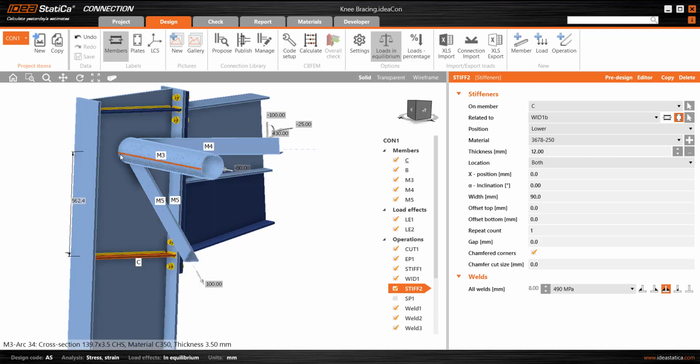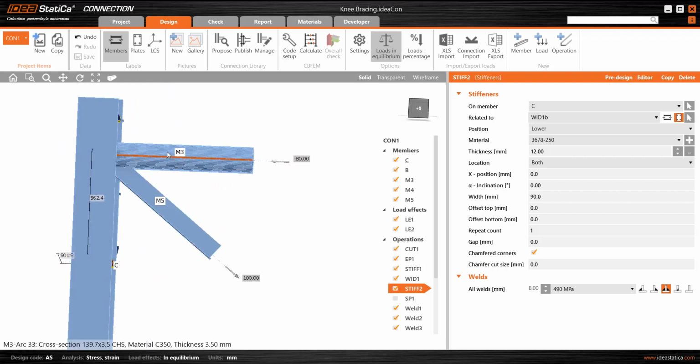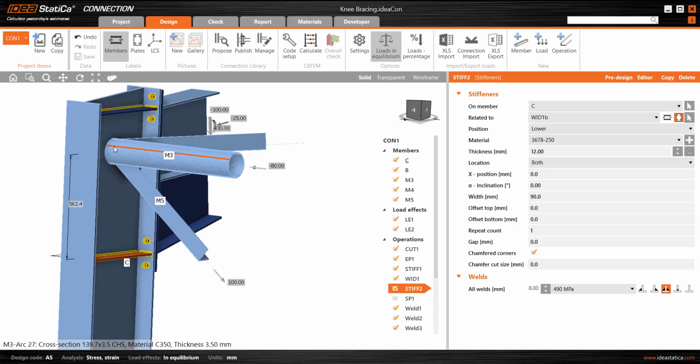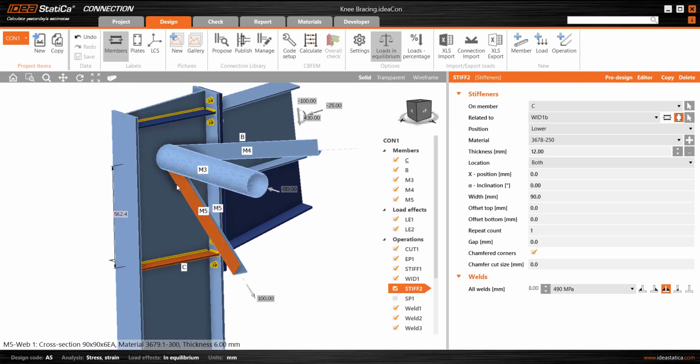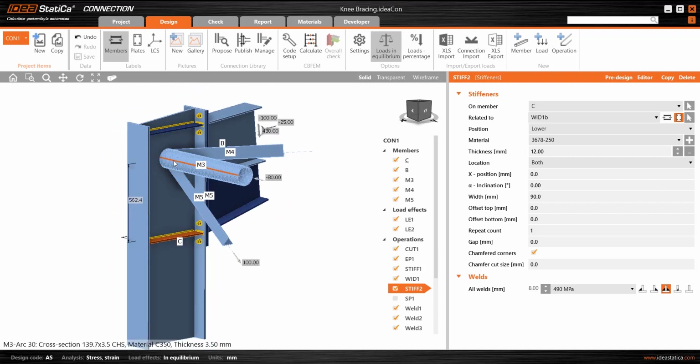Sometimes end plates are used. We need to consider getting the bracing elements in, particularly the strut. The columns might be sprung apart during erection, and you may well be able to use end plates of a sort, or a short stub member. So entirely up to the designer and perhaps in consultation with the fabricator about some of these practical details.